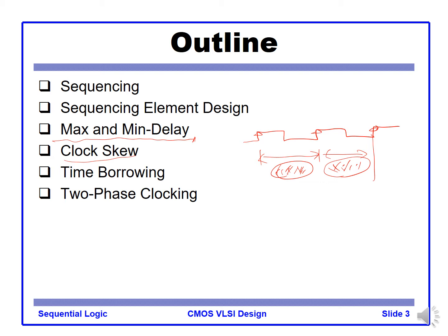We will also talk about time borrowing, how we move this maximum operating point. We can slightly move the operation calculation from this rising edge. We can just delay that. In the next cycle, we will have a shorter logic operation time.